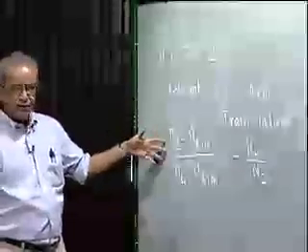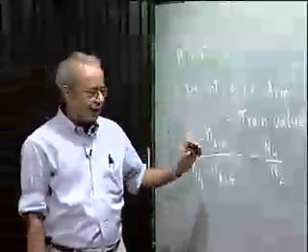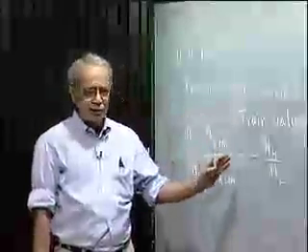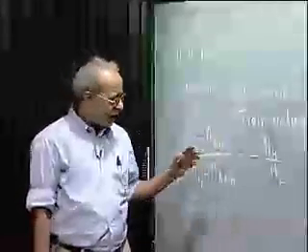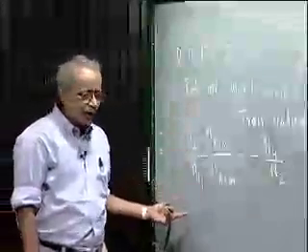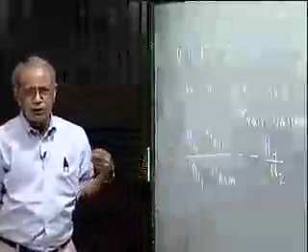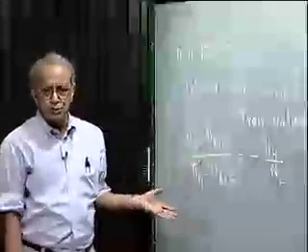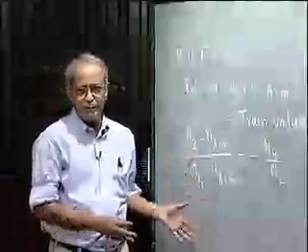And we shall use this for a tabular method, which I also explained, where we talk of two conditions. First, we lock all the elements to the arm, then give arm a particular revolution, then lock the arm and give one of the gears some other revolution and calculate what are the revolutions of all the elements. Then add these two, we get equations in terms of two unknowns, and with two input speeds specified, we'll be able to solve for those two unknowns, and all other speeds are expressed in terms of those unknowns, so we should be able to determine those. This we shall see in our next lecture as examples, through examples.